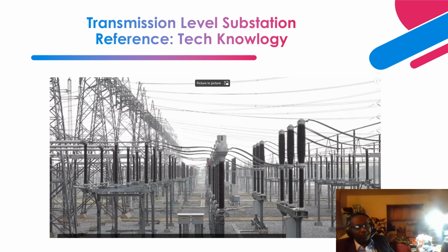Next is another beautiful picture of a transmission level substation. I explained to you in the previous slide, this is an instrument transformer. And this is how you always distinguish between a current transformer and a voltage transformer. A current transformer is connected in series with the conductor, whilst a voltage transformer is connected in a shunt configuration to ground, in parallel with the conductor. This one is a VT.